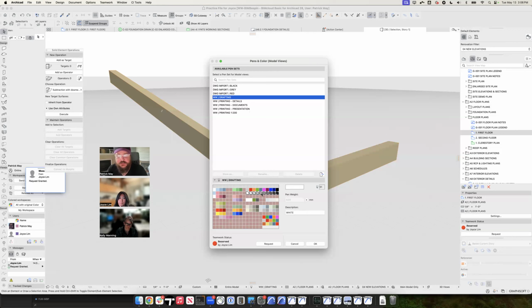These are the fill pens, so that's the fill pattern. If you imagine maybe there's a panelized siding where there are 4 by 6 panels or 2 by 8 panels or something like that. The panels are pretty large, so we might use a little bit darker pen, but all of these are the same pen weight, 0.02 millimeter. As opposed to maybe we've got a 2-inch octagonal tile. We wouldn't want to show that with a super dark pen because it's just going to punch out. So we have super faded pens for stuff like that, where it's a really dense fill pattern. We want to kind of fade it out and dumb it down.